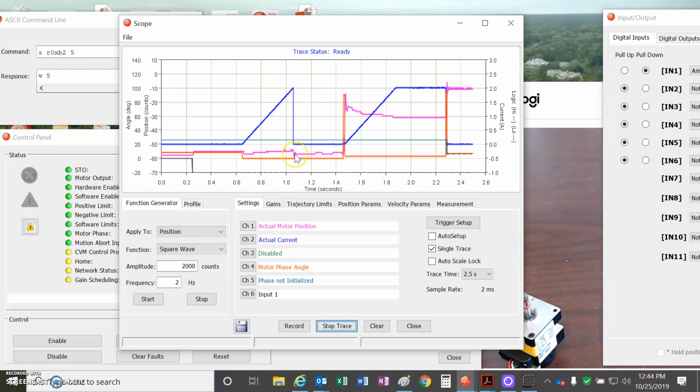And so we see the motor moves or doesn't move very much at all, so only a little bit of actual motor position. And then we apply current again, no current, and then ramp the current up. Now this time we're applying current to a different phase, and the motor pulls. So we've gone from not moving to a little bit of motion, and then we hold it again for another 400 milliseconds to make sure it goes to steady state.